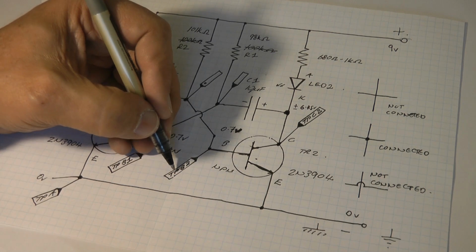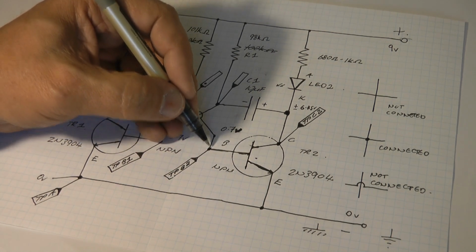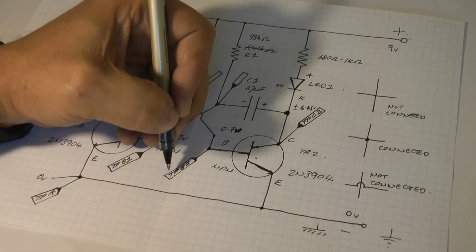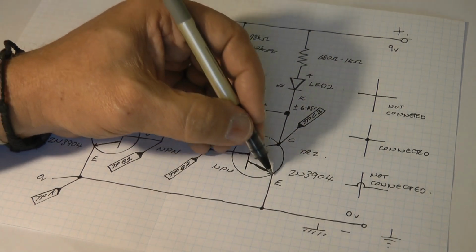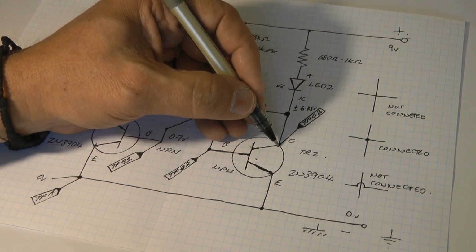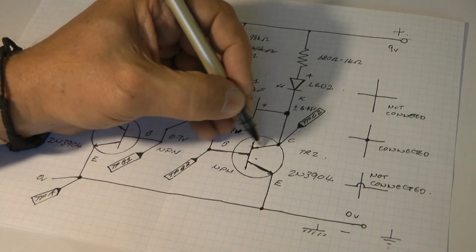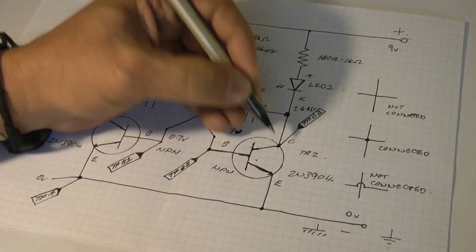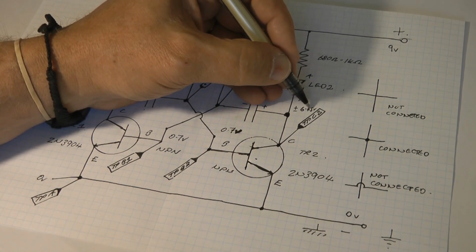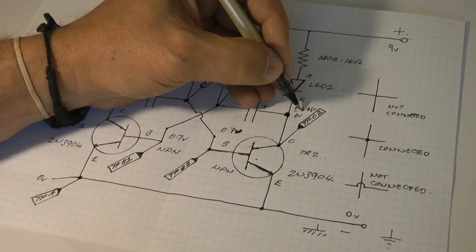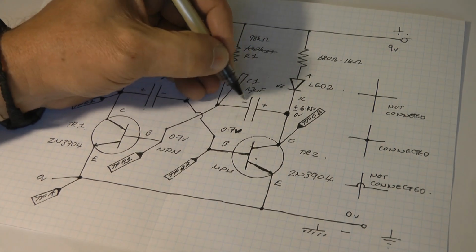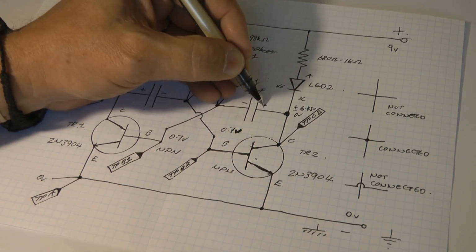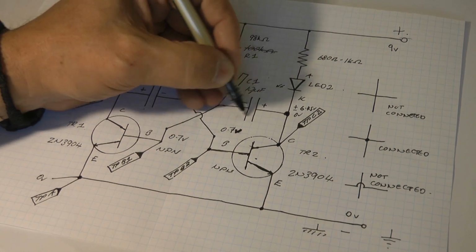Now as this test point on base 2 would have reached the magical voltage, 0.7 volts, and been forward biased, then again, closed contact switch here, which would have knocked this voltage here down to 0 volts over there, and then whatever voltage it would have charged up to over here would have been pushed into minus territory.